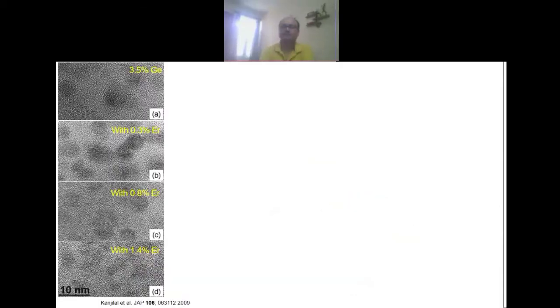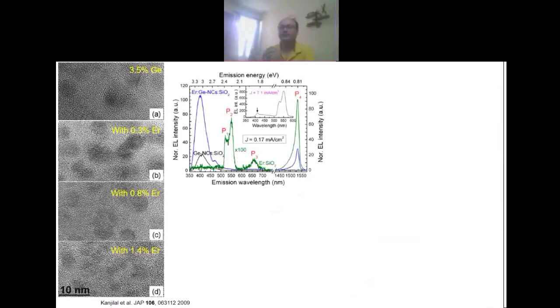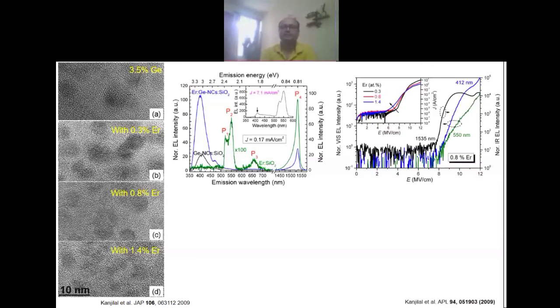But if the structure is not matching, for example germanium compared to silicon with a lattice constant of 5.43, there is a 4% mismatch. That's why you can create some kind of dislocations at the interface. But here you do not expect dislocations because they are lattice matched.